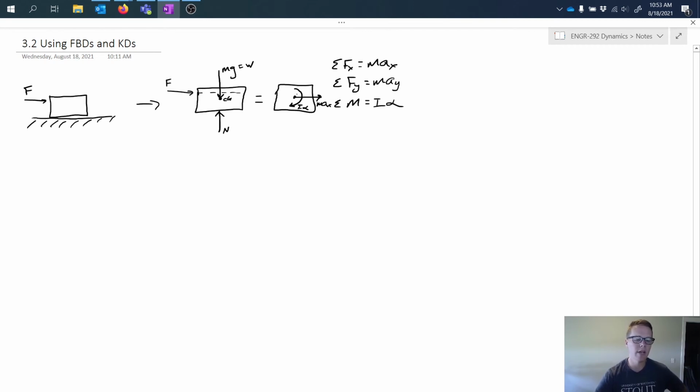and I suppose in theory I could draw an arrow on here to indicate possible acceleration in the vertical or y-axis direction. However, from our problem, if this thing has mass and it's constrained from moving down by the floor, then likely the acceleration in the y is 0 in terms of it actually moving, right? Of course, we have gravity, but the gravity is represented in this case by the weight of the object. So as a net result, we could probably leave that off, but for completeness, I'll put it on there.